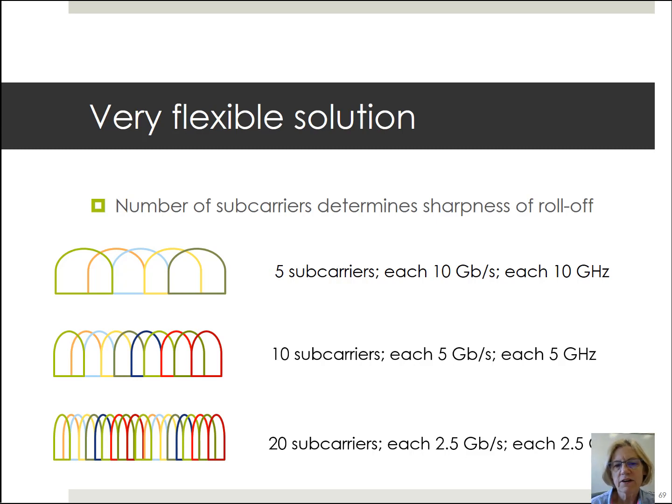And I want to mention another advantage of going to OFDM in terms of DSP complexity. In that case, I'm looking at the equalization that I would have to do at the receiver end. Equalization is the digital signal processing used to overcome a variety of impairments that could arrive during the physical layer link.